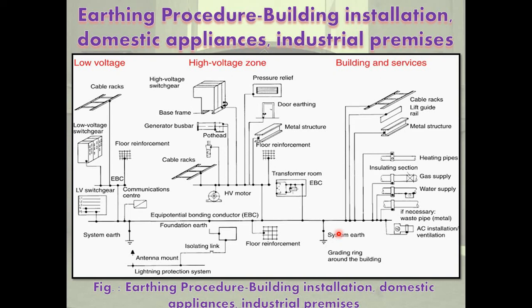Now, in residential lighting control, residential wiring for small connected loads below 1.5 kilowatt is with a single phase supply through a single phase energy meter, switch and single phase switch fuse combination. After the main fuse, branch fuses are provided for grading of fuses. For a connected load of 2 kilowatt and above, a 3 phase 4 wire supply is provided. The incomer switchboard has a 3-phase energy meter, a 3-phase master switch fuse unit and branch fuses or MCBs.